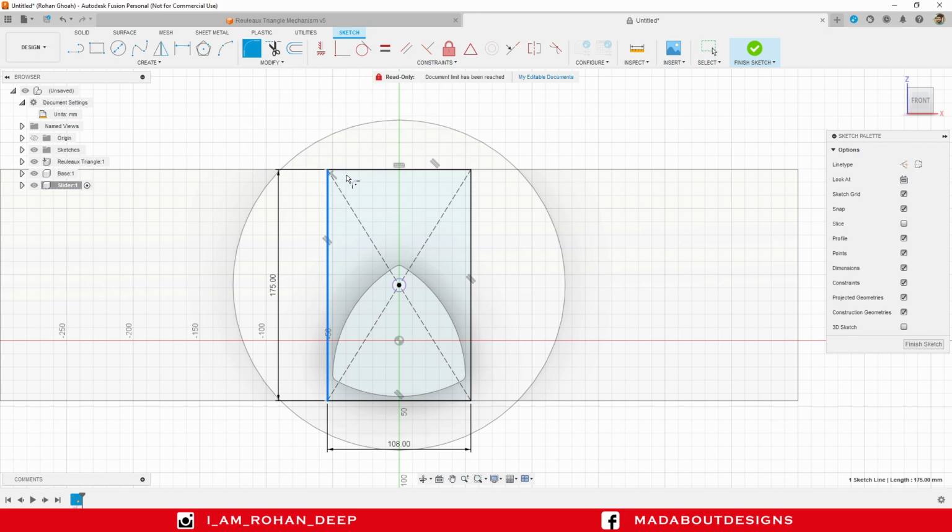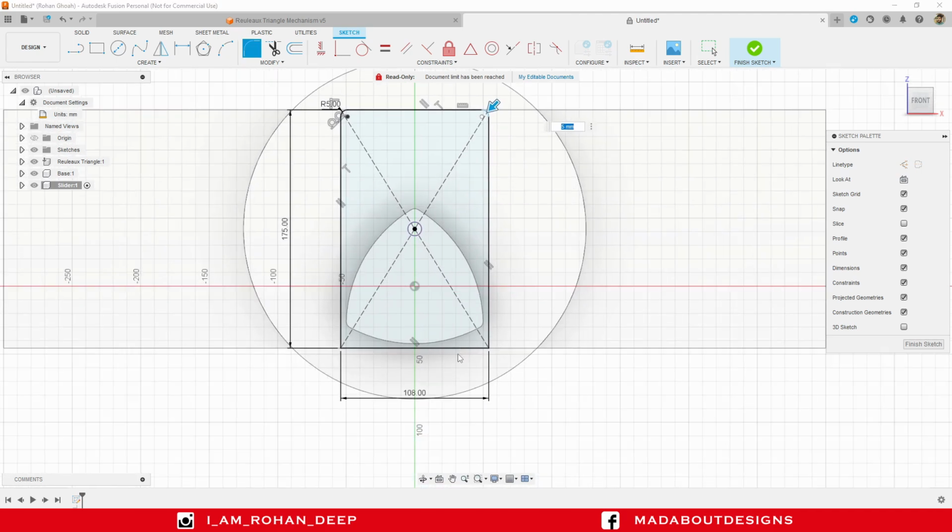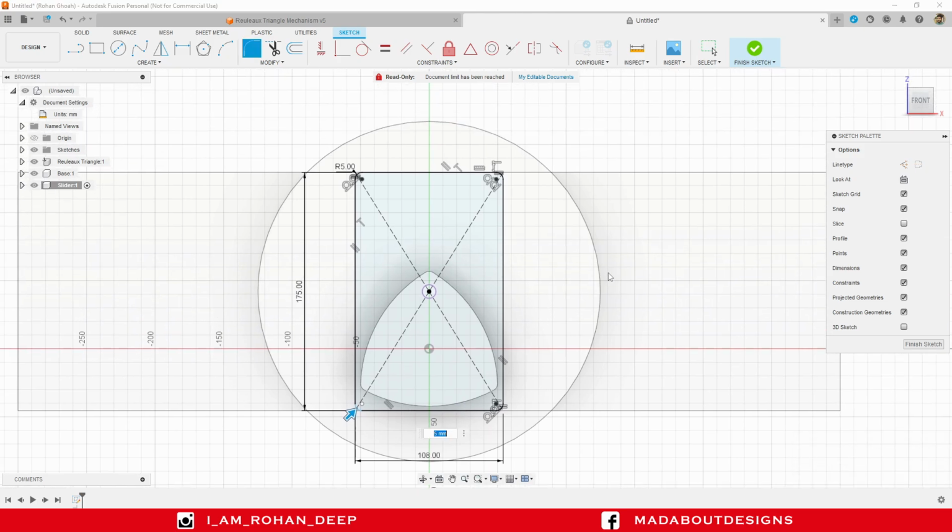Select these two edges and provide a fillet radius of 5 mm. Now keep selecting the other edges so the corners between them will be filleted at a radius of 5 mm. Press Enter. Hide the constraints.